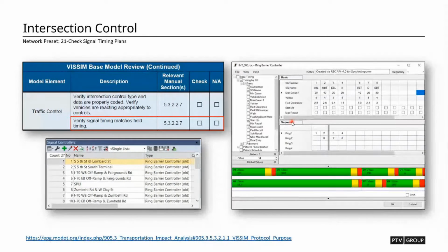Typically where I will start is I'll start in my signal timing plan, right? You'll have like 4 or 5 pages. One of them will be your schedule. And so you'll look at, maybe you're in the AM mode or the PM mode, right? And so you'll look at the schedule and you see what pattern should we be operating on, and are my splits okay? So you can look at your splits down below and make sure that your splits match up. And then you'll go back to that first page that says green timing and red timing and things like that, or yellow timing, and you'll make sure all your clearances are correct and all of your phasing numbers are correct and things like that.